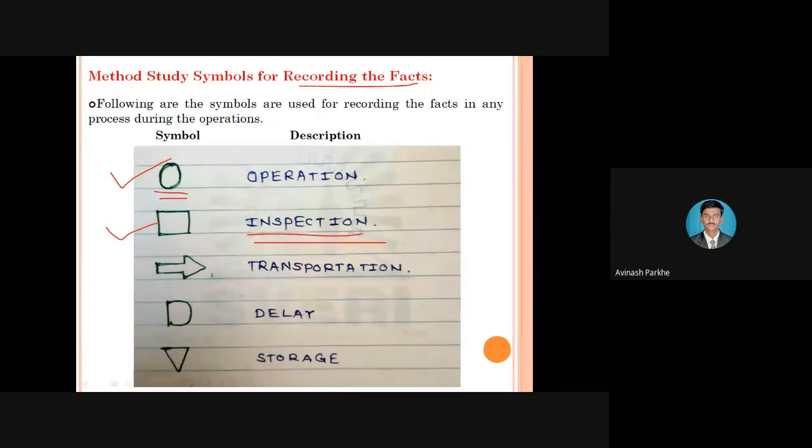The diameter has gone from 50 mm to 45 mm. Again I have to reduce the diameter by 5 mm, so I will perform the turning operation again. Again I will check that diameter. If that diameter is 40 mm, then I will stop that operation. That means for some products, inspection can be carried out after performing all the operations.